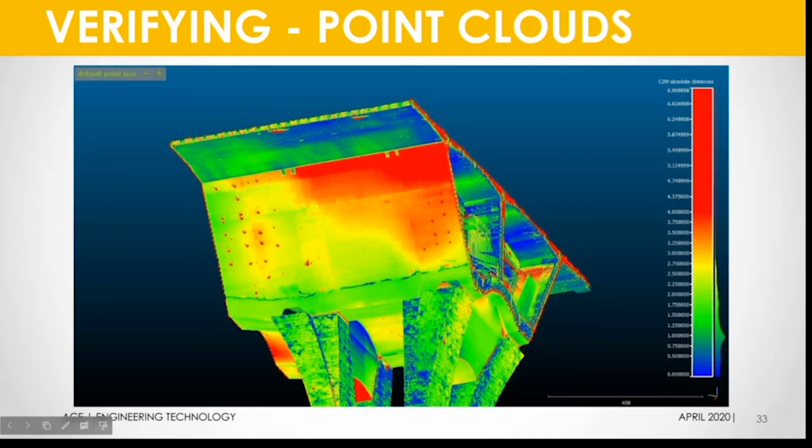So in this case, this is a bridge structure about 100 feet wide, about 90 feet in the air. And all of the concrete formwork that's supporting this, right, believe it or not, when you pour concrete into formwork, that formwork does move. Now, mind you, it may only be fractions of an inch, but in some projects, you can have very tight tolerances where fractions of an inch really add up and matter. So in this case, to actually verify that this really large structure was still within the allowable tolerances, what we did is we went out and laser scanned it and compared it to the model.